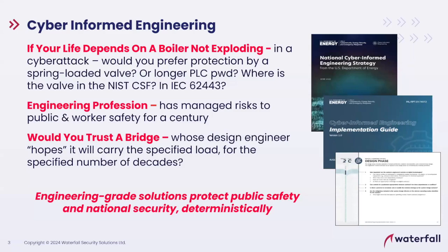What does that mean? Well, in a large power plant, let's say an old-school, old-technology coal-fired power plant, we've got, let's say, 6 generating units. We're producing 1.5 gigawatts of power, 1,500 megawatts. Each generating unit produces 500 megawatts. What's a generating unit? Coal dust is fed on a conveyor and blown into a furnace. It ignites almost instantly and is consumed in about a second, turning into carbon dioxide, which we don't like, and of course water vapor, and traces of other contaminants, and produces heat.